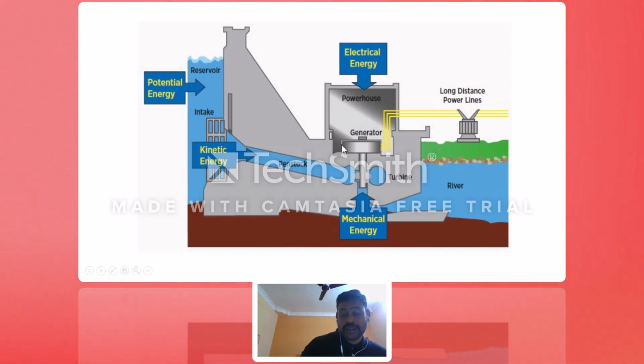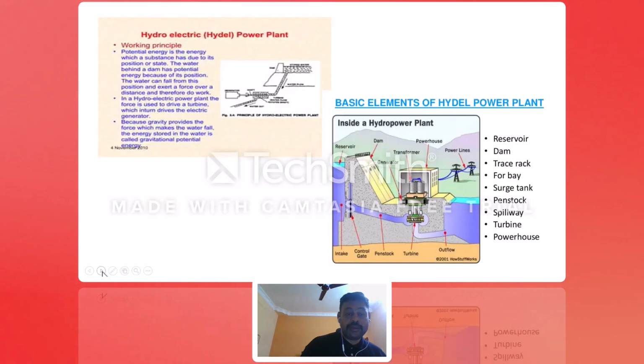Now we will go to the electrical energy generation. While rotating here, you have a generator. Generator means coil and magnet. Here we are providing the relative movement: the mechanical energy, the turbine rotation, gives the relative movement between the coil and magnet. Therefore, according to Faraday's law of electromagnetic induction, power is generated. The generated power is tapped out and supplied through this line. This is the simple concept of a hydroelectric power plant.